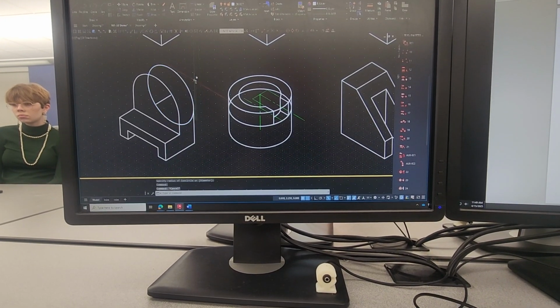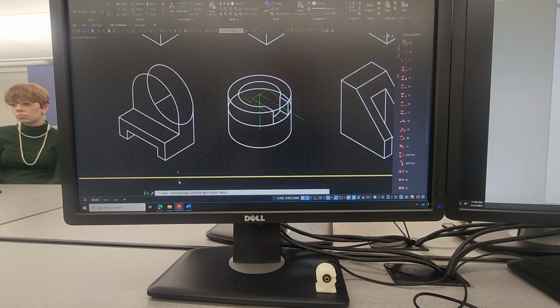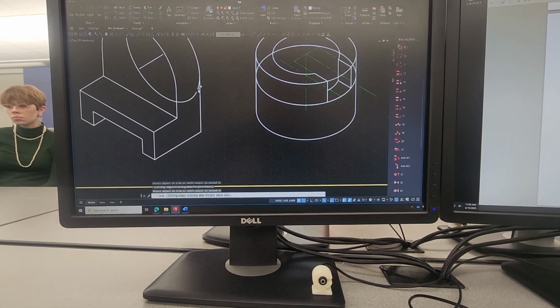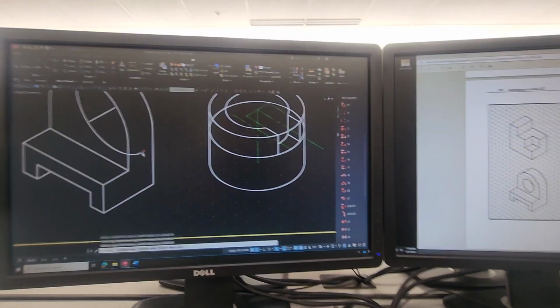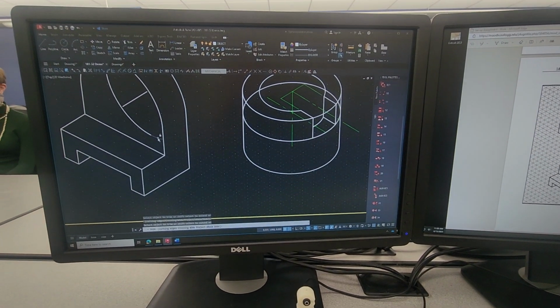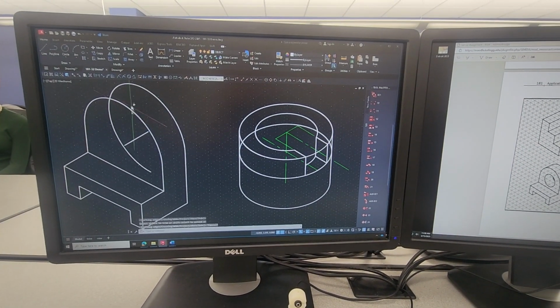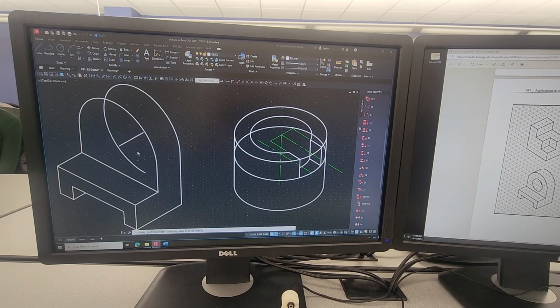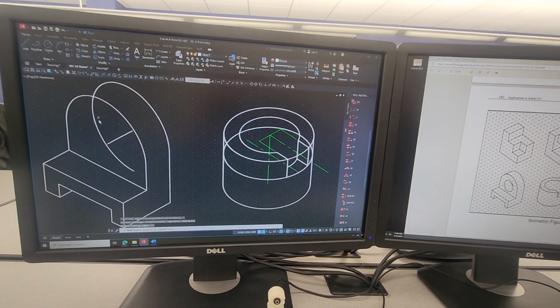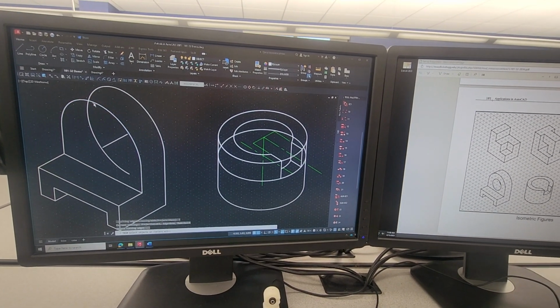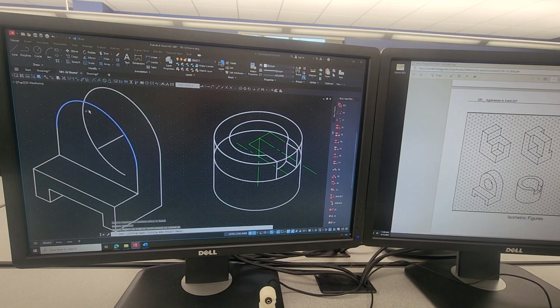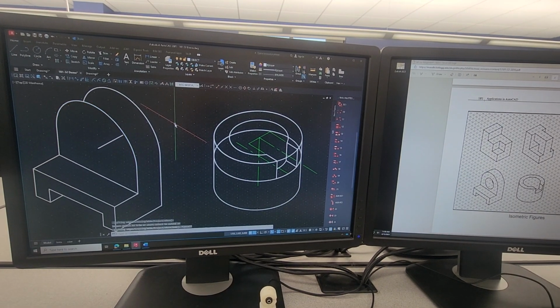So again, if you choose to trim now and you want to trim this stuff out, you're only going to get little pieces of flex like that because it goes between the grid, and that could take you forever. That's why I'm saying use the trim command, but choose that cutting edge and say I want you to be cut off at that guy right there, and I will make it go away to that point there. Yes, Ray?